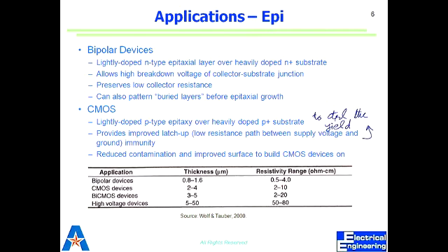So you have N+ heavily doped, but now you're growing single crystalline material on top of that, which is lightly doped. So your heavily doped layer is now buried in between. It's not going all the way. It's of course a limited depth that has that high concentration. So then how does the rest of the substrate form below the buried layer? That is lightly doped. That is supposed to be oppositely doped, in fact. If you have P-type substrate, you make your N-type well to make your devices. That's the CMOS. So you always have the opposite doping in the bulk.